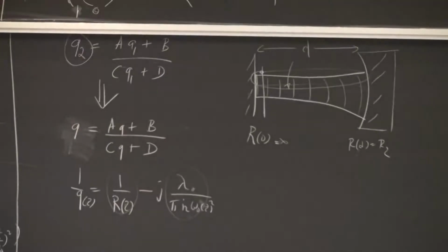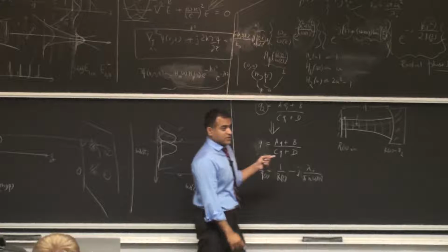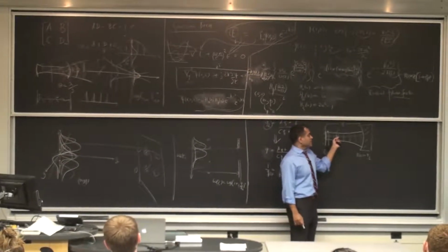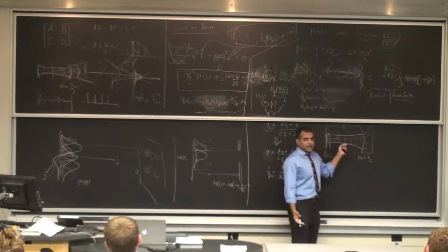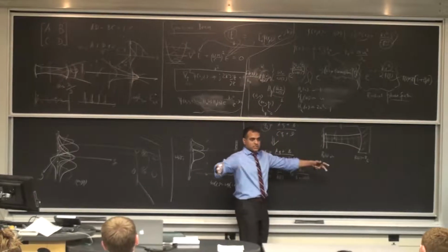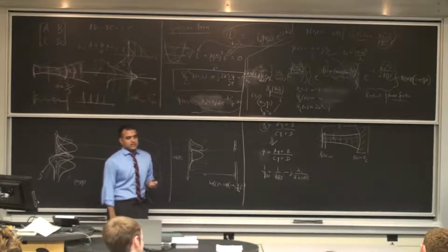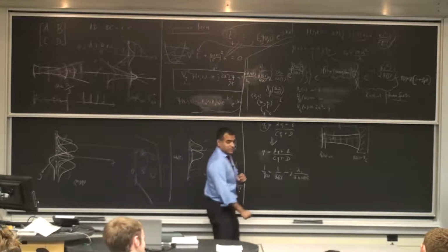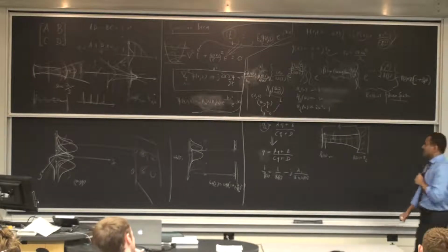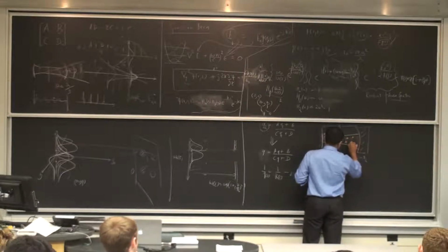What's the volume? And the reason for that is, as you know, just putting a cavity like this is not of much use till you have gain in the medium, right? We want to have optical gain in the medium to make it not die out. You have a resonator plus a gain, which will give you a sustained oscillator, and the gain is always by stimulated emission. That's what we use in a laser. For that we need matter. We need to put in some atoms, or a quantum well, or quantum dots, whatever gives me my stimulated emission. So I will need to populate this region with my gain medium, right?